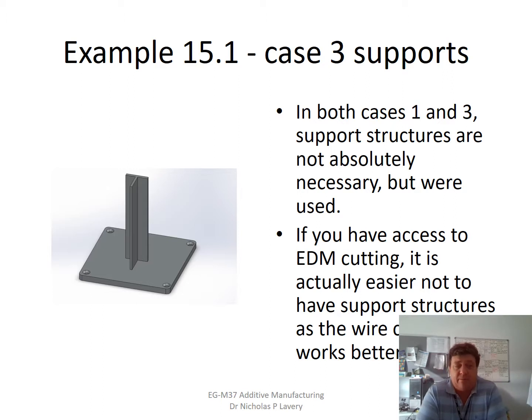You could potentially build a part vertically off the plate without any supports, but then you're going to have to cut it off. So if you have access to the electric discharge machining that we do in the workshop, then that's a relatively easy job. But let's have a look to see. We will make it in this case without support structures.